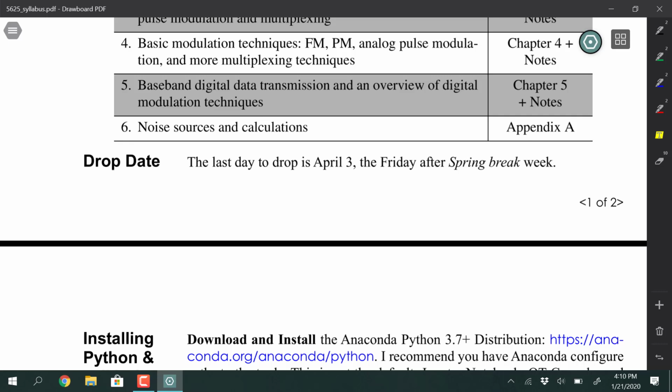And GPS, you have to synchronize to that spreading code in order to get the time difference of arrival off of signal 1, signal 2, signal 3, and then triangulate to get the position. It's all very cool stuff, but synchronization lies behind a lot of the digital comm stuff. Without it, you have nothing. You probably never thought that way. You thought, I turn on the radio and the signal's there, it's good. But digital communications, it's not good. You got to have synchronization because you have asynchronous clocks floating around.